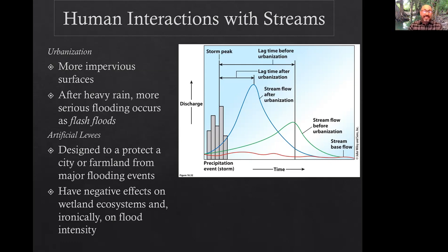And the river isn't built to handle that rapid influx of water. It expected all those water droplets to percolate down through the soil water belt and slowly get released into the river channel over a greater amount of time. That's the green line in this graphic. But because we have caused the water to run off faster and get to the river channel sooner, this is the new input curve to the river.